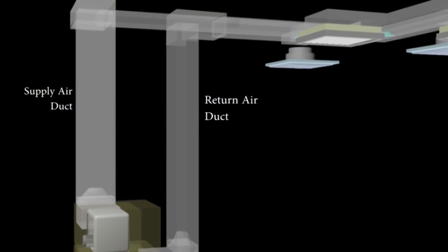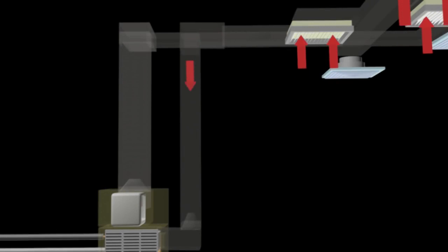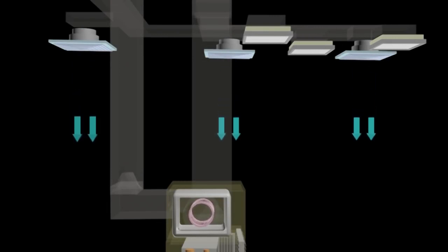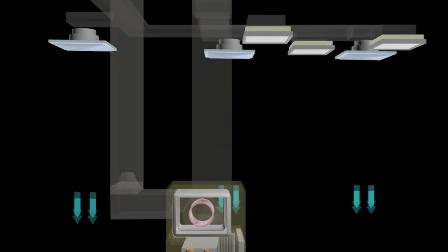These air ducts are coated with insulating material consisting of fiberglass wrapped with aluminium foil. It reduces heat transfer from the environment to the air duct. Air returning to the air handling unit will pass through the filter before passing through a cooling coil and returning back to the room. This is to ensure that the air returned into the room is in a clean condition.